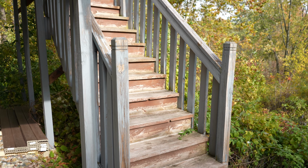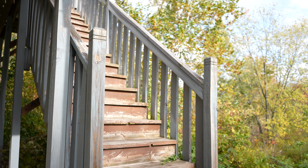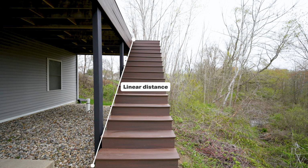Accurate measurements are crucial when it comes to properly engineering and manufacturing your cable railing system. Each space is different and should be measured with care in order to collect the most accurate dimensions. If your space has stairs, you'll need to measure the rise and run of the treads in addition to the linear distance from the top and bottom of the staircase.